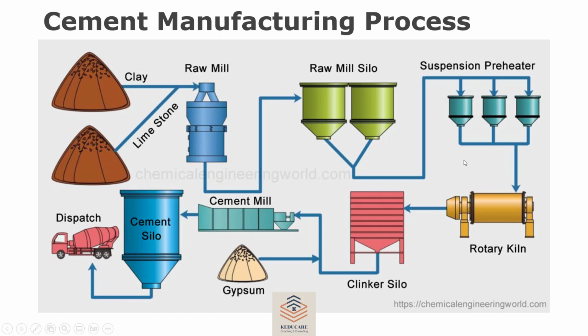And then the lower part comes, where the temperature reaches up to 1500 to 1700 degrees Celsius, and this part is known as the clinkering zone. The final product that comes from the kiln is called clinkers. Those are small hard balls. The calcareous and the argillaceous materials react to form calcium silicates and calcium aluminates in this lower part.